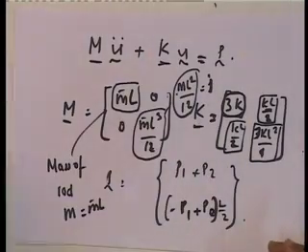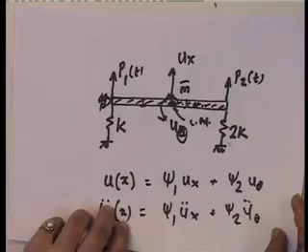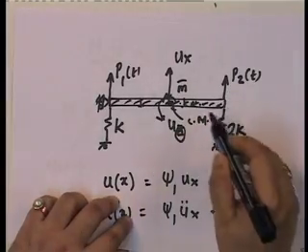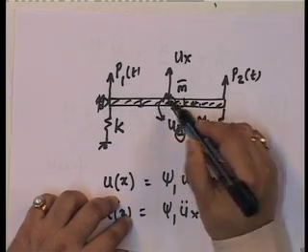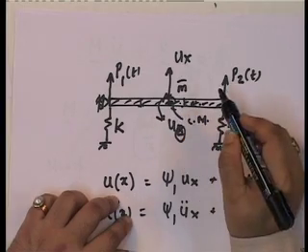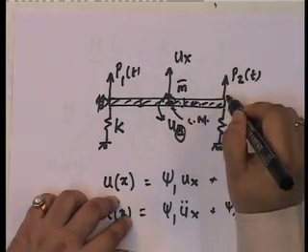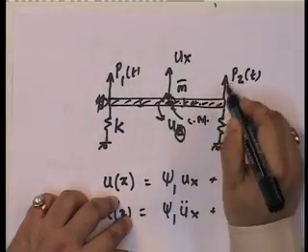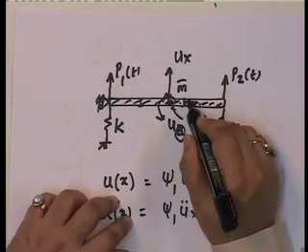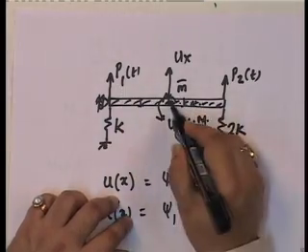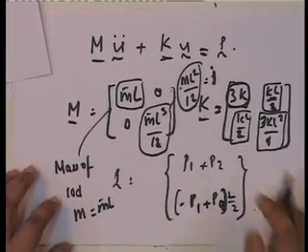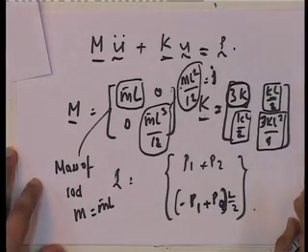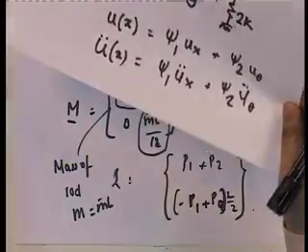So these all have physical meaning. If you look at P1 and P2, P1 plus P2 is the load. And what is the net moment? This one has negative, this has positive, so this is P2 into L by 2 minus P1 into L by 2, which is the net moment here. So you see all of these terms have physical significance in the entire scope of this problem. And therefore, coming back to it, if we look at it,